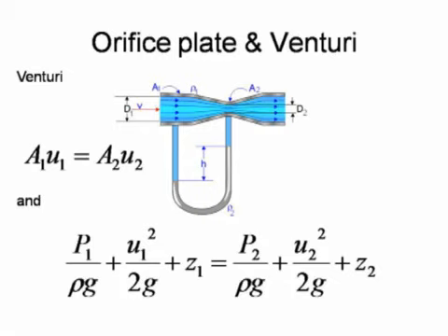Taking the venturi, we have the flow constricted down to its narrowest point, and that's marked as having an area A2. The flow approaching the constriction in the full bore of the pipe is shown as having an area A1. Those are internal areas A1 and A2. And the pressure difference between those two positions in the pipe is measured as that height marked on the manometer there. Well, we have our two famous equations here in fluid mechanics.